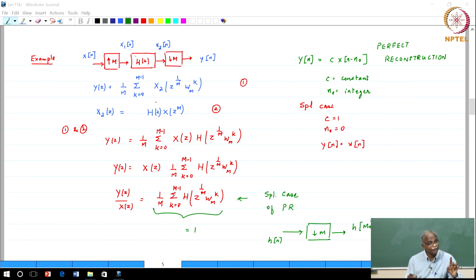Okay. If I have done that, then what would have happened? I would have restricted my signal to minus pi over m to pi over m, correct? That operation would have taken place correctly. This is in the context of interpolation. So, then I downsample by a factor of m, I will get back the original signal, whatever was the original signal, from minus pi to pi.